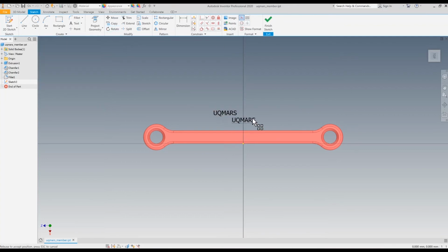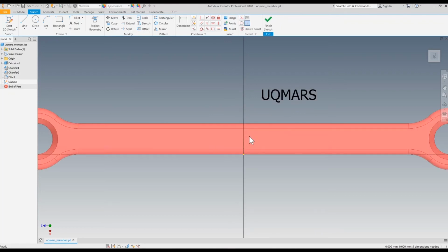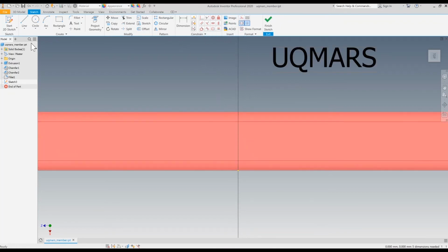All right, so now we want to position this exactly in the center. So let's use our center lines, and we'll create a center line. The height does matter for this one, and the reason being is because our second center line needs to be in the middle because we want a nice even split. All right, that's a good start. Now let's go dimension. If we dimension this way, we'll see that we have 1.284. So let's just leave that dimension there, and this way 5.379. Okay.